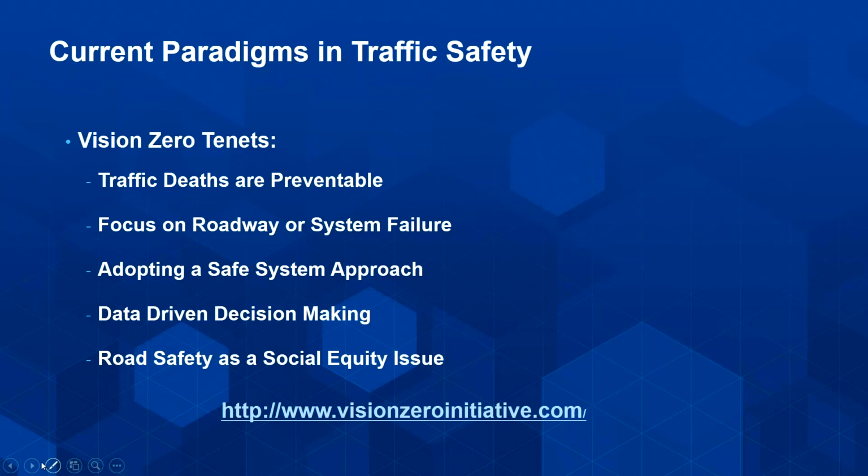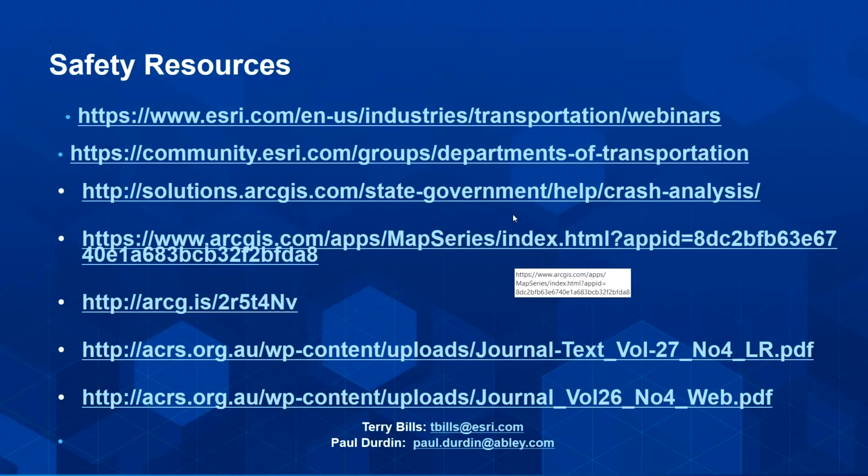So we need to understand the type of intersection form, whether it was a 3, 4, or 5 or more leg intersection, what the type of controls that exist at the intersection, whether it's a signalized or a yield control or a roundabout, and also the speed environment, because all of those factors, the speed, the intersection form and control, have an impact on the likelihood of death and serious injury for a particular crash movement type. So we need to understand those features as well as those commonalities amongst crashes.